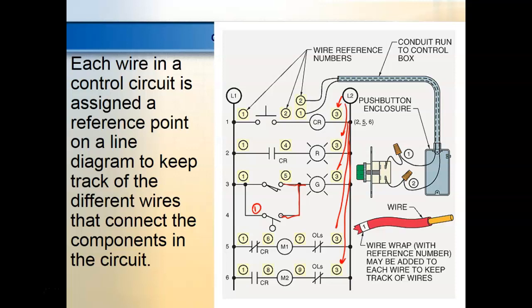Electrically it's the same. So if you've got a wire that you're running, and they're side by side and you're running down here, that would be a more efficient way to do it. I'm not going to make you tear down your circuit and redo it. We're going to use what we call a two-terminal rule, which means on the power supply, no more than 2, one on L1 and L2. And then after that, no more than 2 jumpers on any plug. And you'll learn that you can figure out how to jump more than 2.